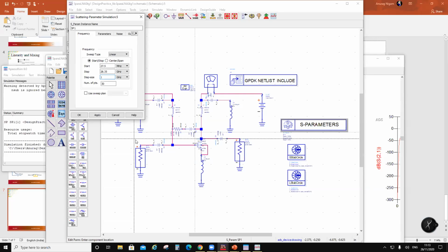So the problem with traveling wave amplifiers is you have to have a directional flow of waves to the output, not backward. That's why the efficiency numbers are poor on a traveling wave amplifier if it is just designed by the theory of a transmission line. You have to use tapered lines to make sure that the waveform is always in the forward direction, and the reverse direction waveform is very small. So that's the caution in traveling wave amplifiers. I can do a workshop on amplifiers only, but right now this is not the workshop for that.